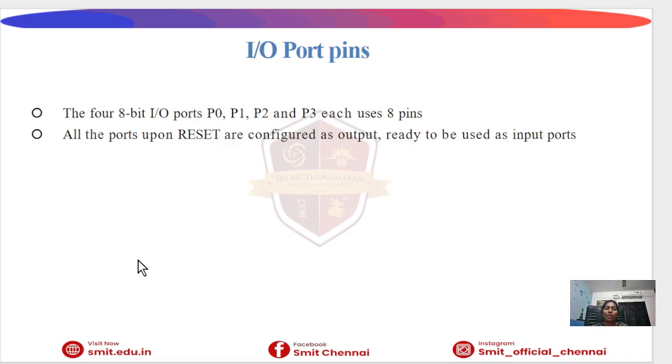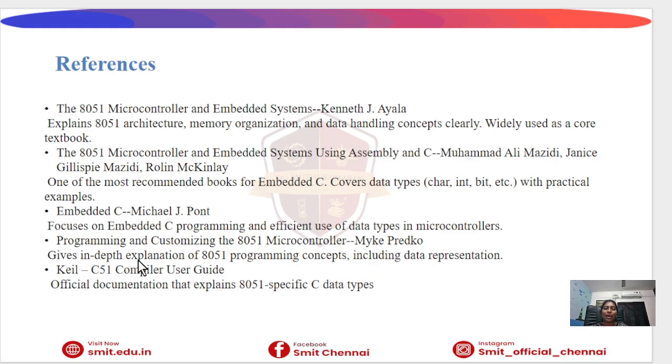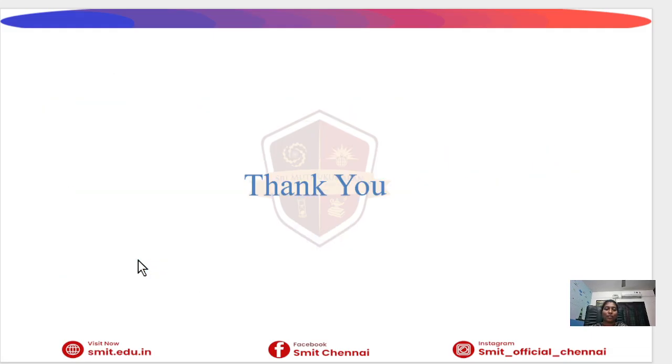What are the topics we have seen? To summarize, we learned the history of the 8051, different 8051 variants, and important pins like XTAL, reset, EA, PSEN, ALE, and input output ports. In the next video, we will move to programming concepts and applications. Thank you for watching.